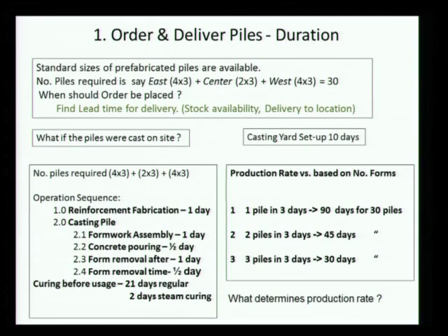How would it change if I was fabricating the reinforcement on the bed? It will add 2 days. It will constrain the resource of the bed till that reinforcement fabrication is also completed. In piling, did we assume that? We will have to go back. You can go back and see in piling if that is assumed. So we would have assumed that it was fabricated on the bed.